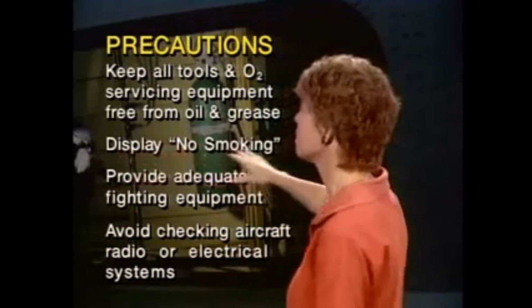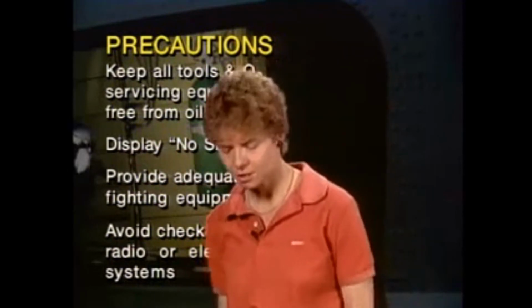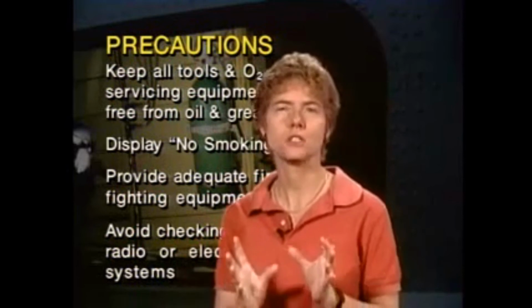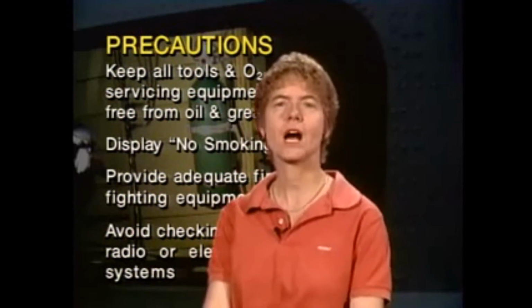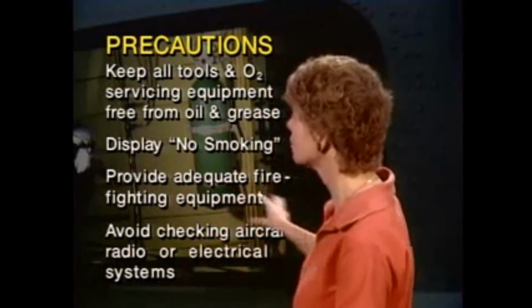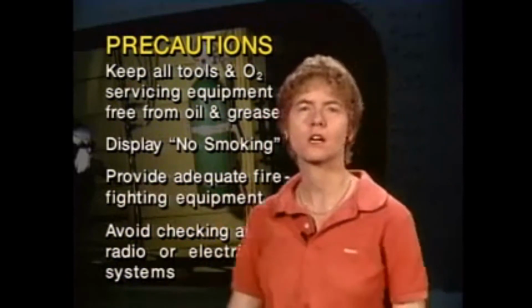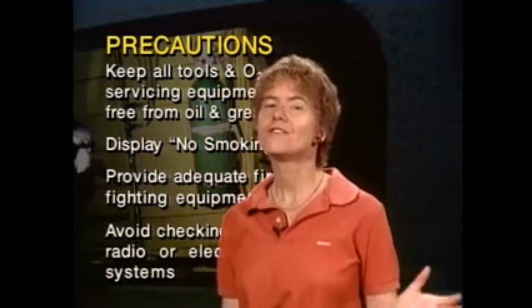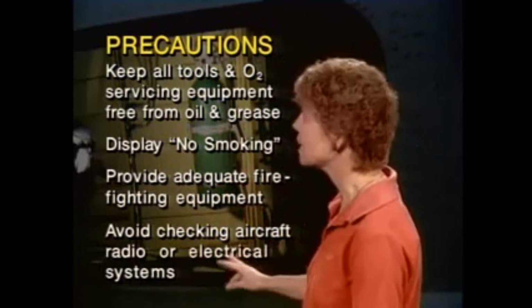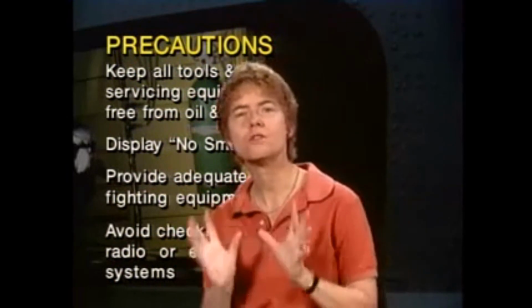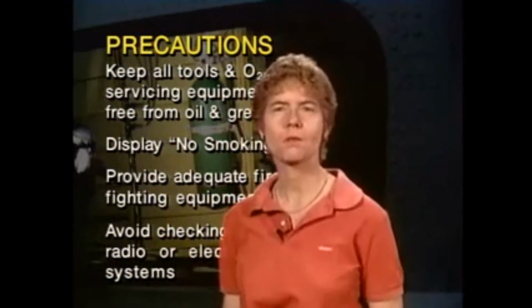You want to make sure that you display no smoking placards when you're working on the oxygen system because, again, oxygen is extremely flammable. Because of that, you want to make sure to provide adequate firefighting equipment in the area when you're working on an oxygen system. And you do not want any sparks, so you want to avoid checking aircraft radio or electrical systems. You don't want any sparking problems.